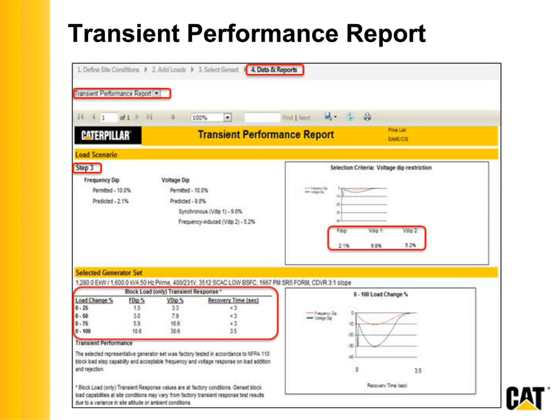And again, it's at 25% load change increments. When we test a genset in the factory for transient response, we test it at every 5% load step to better accurately document its transient response. So this is a report of the genset that you selected of its transient response.